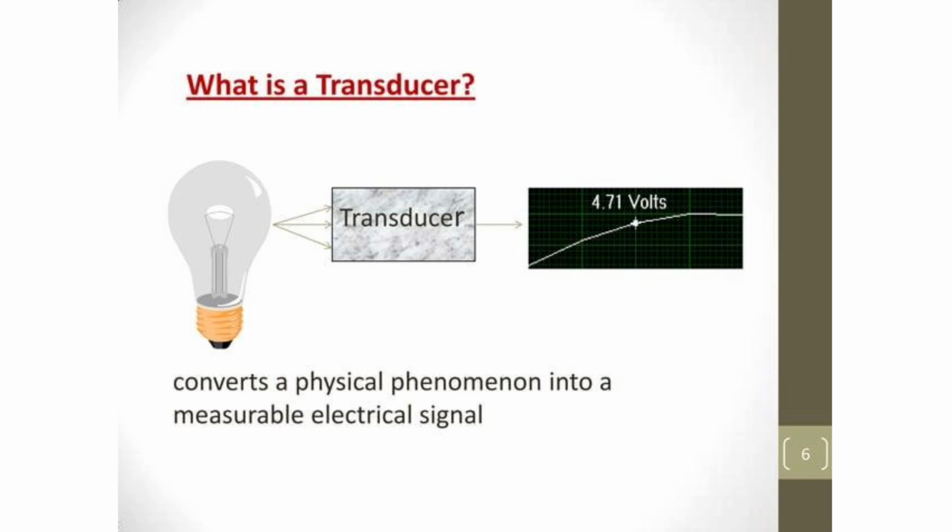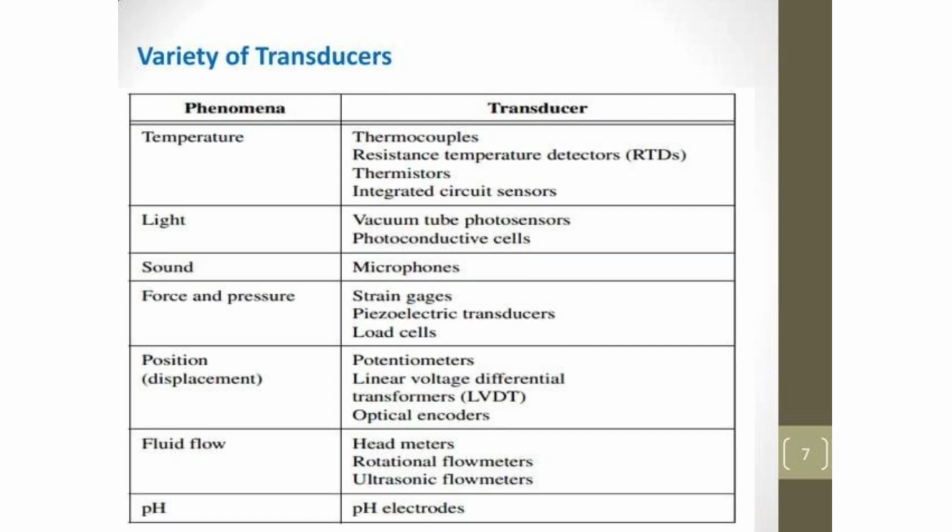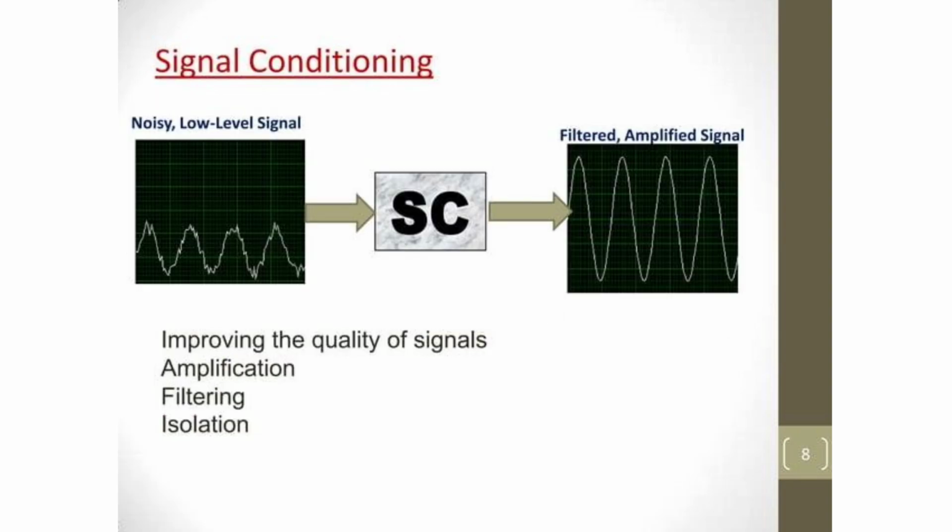Here the process begins on the far left with the physical variable that undergoes the measurement, and the sensor transforms the variable into a raw analog signal. Because the raw signals are often very weak, frequently in the microvolt or millivolt range, and highly susceptible to noise, they pass immediately through the signal conditioning block.